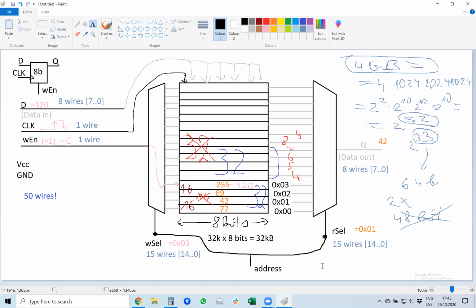This is why all processors, all microcontrollers have this thing that if you want to copy memory from one location to another, one number or 500 numbers, doesn't matter, you first read the number into the processor, into this general purpose register block, for example, register R5. And then you store the value of register R5 in another location that you select with the next address. So you want to read, for example, from address number 0 and copy it to address number 3.